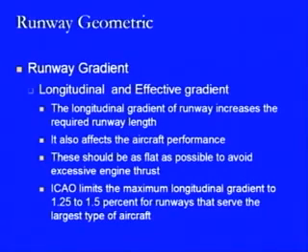then at the point where the two gradients meet each other, a kink is formed, and as the aircraft traverses this kink, there are chances of structural deformation coming within the aircraft. So the amount by which the two longitudinal gradients have been connected with each other, that is, the steepness of those two longitudinal gradients, will define the amount of damage which may be caused to any aircraft.